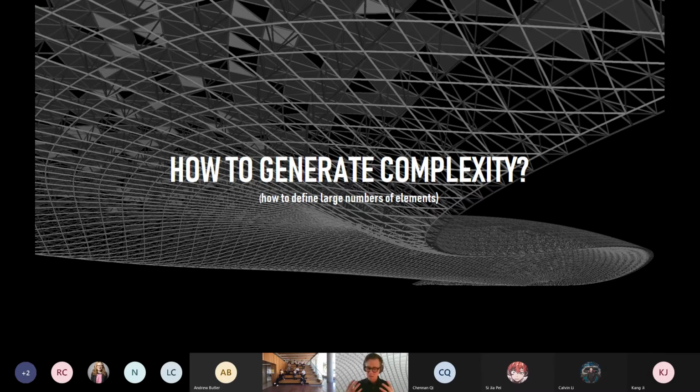So we needed to develop structure at a much finer resolution. And so we started looking at space frame geometries, working with the engineers Arup to do this. And we realized that the number of elements that we were going to have to draw was massive, just massive. And these parametric tools, like dimension-driven design, while they were good for defining the guide curves for the Swiss Re office tower or for the form of this structure, they simply didn't scale up to generating this complexity, these 200,000 elements, a minimum that we would need for the space frame.